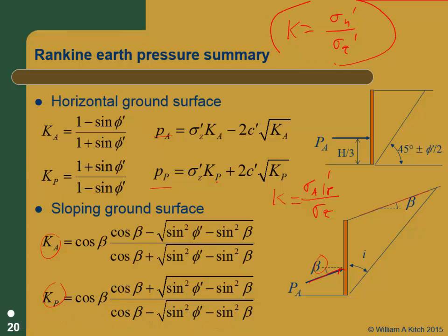We always tell you that this is the equation for K, the ratio of the horizontal to the vertical stress. It's the first thing we tell you about horizontal earth pressure: you take the vertical stress multiplied by K, you get the horizontal stress, not necessarily having anything to do with walls. That's just what we tell you the definition of K is.